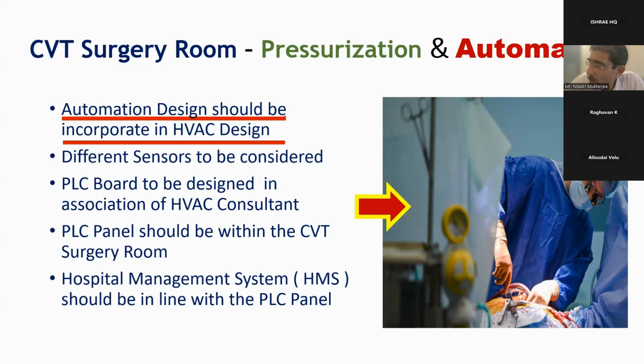What other option? See, this I told you, is being suggested by our consulting organization from Singapore for a particular hospital project. These are guidelines, not standards. But this is the method which shows how it can be controlled. For these types of 14-hour, 12-hour surgeries, the major thing is to control the pressurization. They recommend a dedicated AHU so that contamination becomes less.